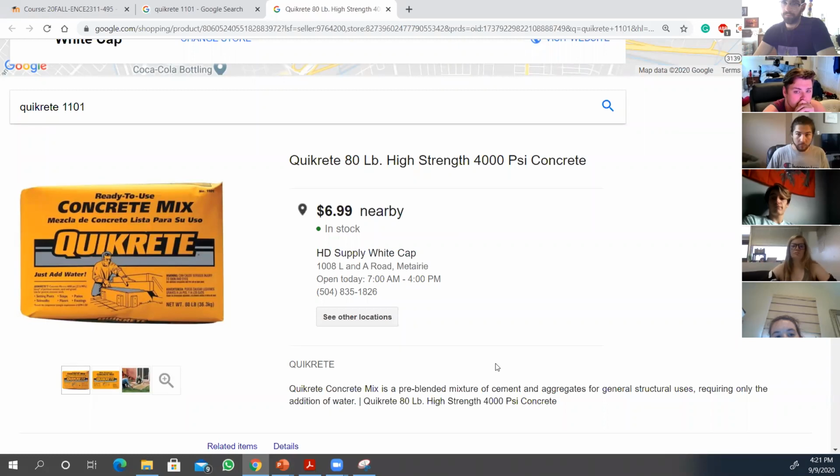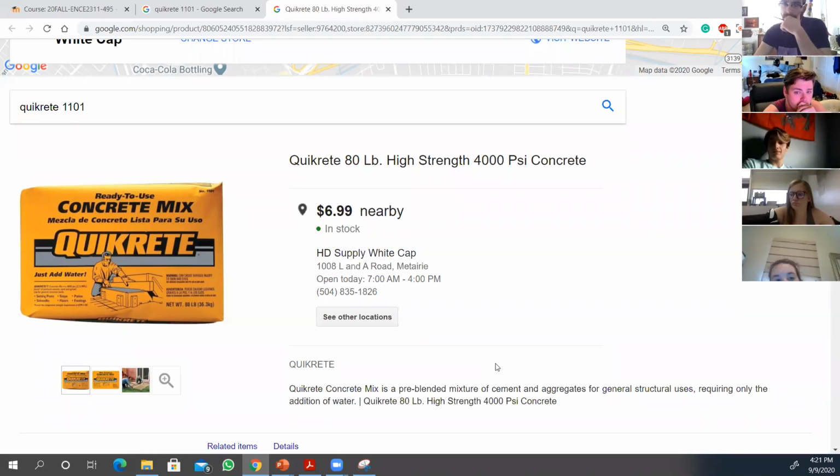If you add more water, you're going to lose some strength. It's like you're making a soup or pasta, but you add more water. You're increasing the volume, but reducing the taste. Same way, you increase the volume, you increase the workability of the concrete, because if you put more water, it's going to act like fluid, right? So it has pros and cons.